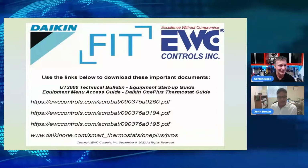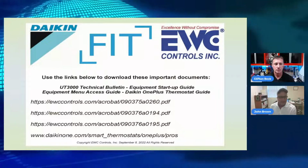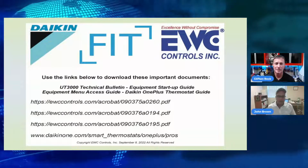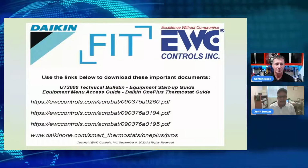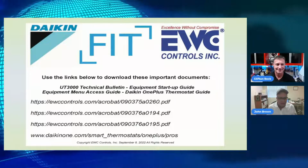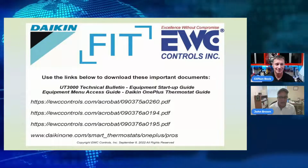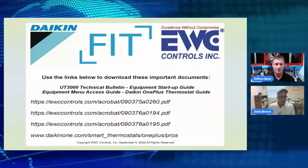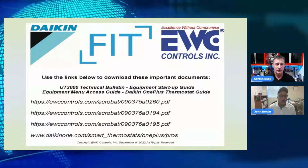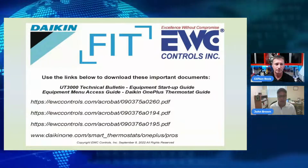Such an important topic. As I said, once again, it's really important. No matter what manufacturer's communicating equipment you're working on, these communicating systems are not going to go away. The higher the SEER requirements, and the government's about to release SEER 2, the more prevalent these communicating systems are going to become, because you can move a whole lot of information, a whole lot of data. You can have high SEER multi-stage inverter proportion equipment with just 4 wires. Not going to go away. No matter which manufacturer you're working on, if you know what the voltages are supposed to be, and if you know what the delta between these data lines are supposed to be, you can create a good, stable highway for the data to move on, and your system will function.